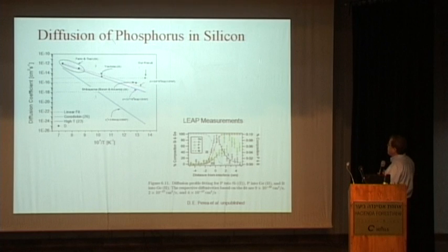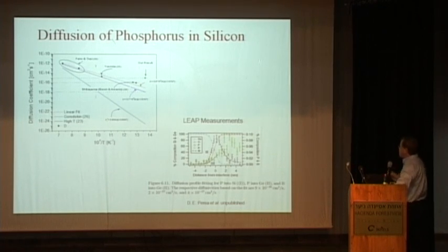So what we have found here for the first time, and to our knowledge nobody has measured the diffusion constant in nanowires, is that the diffusion constant is at least 1 order of magnitude larger than in bulk silicon. So if people want to make devices from these nanowires, they have to solve this problem. This probably can be solved by annealing, and we are working on this right now.